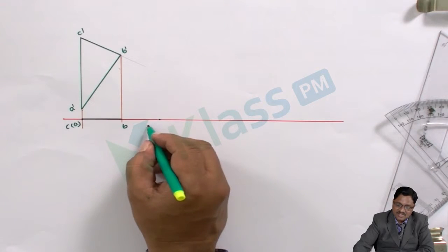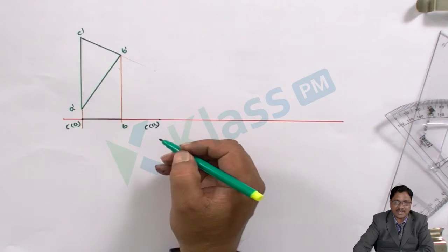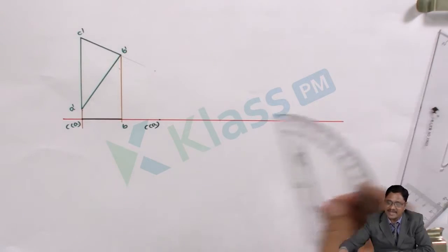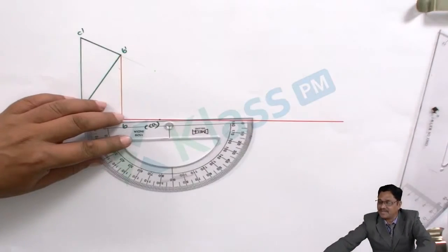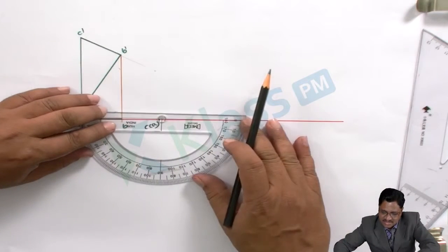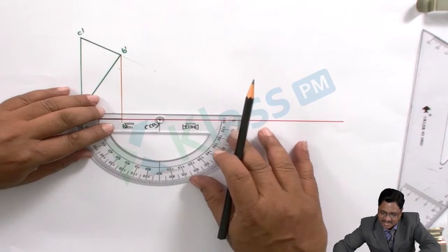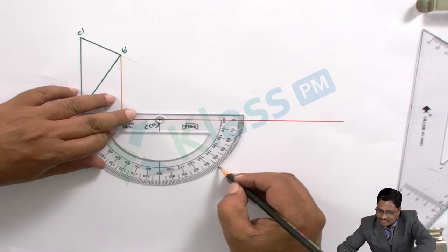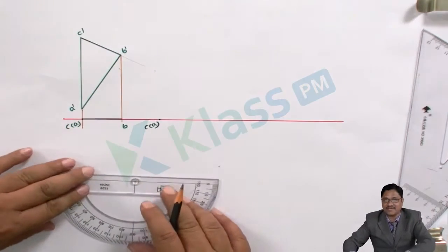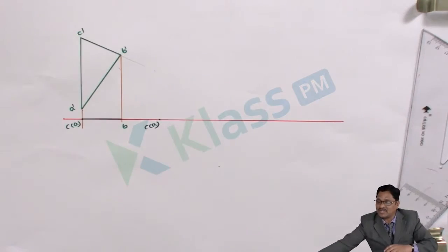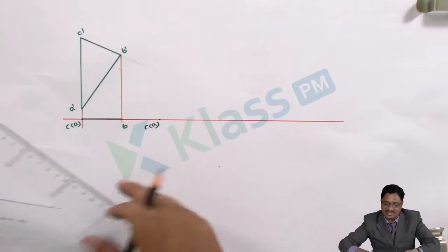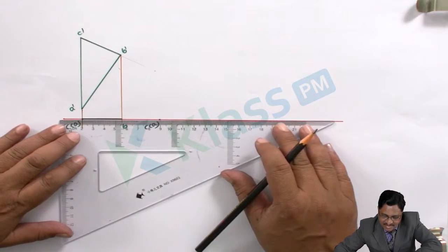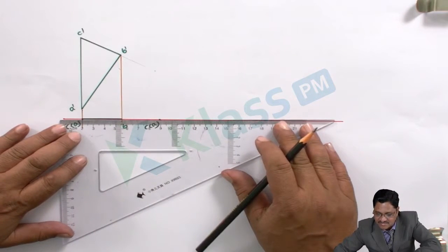Just as I am pointing, this is C in the brackets A, with the direction of angle 45 degrees. Again, take the protractor with the angle direction. Since the surface is making 45 degrees, place the protractor at the proper point and measure the angle of 45 degrees. Along this 45 degrees, what is the length to be drawn? Dimensionally there is no change, so you just measure the length here, and the same length is to be transferred there.